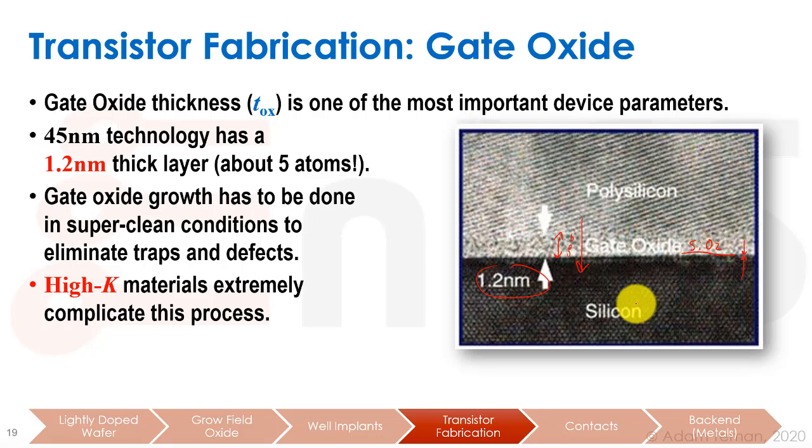There are other reasons, for example, that it's sand and we can find it all over the place, and it's cheap and easy to use. But to make MOSFETs, this interface between the silicon and the silicon dioxide was very important. And changing our materials several years ago to high K materials, which are not silicon dioxide but are based on hafnium and so forth, is taking our basic assumption of a good interface between the silicon and the silicon dioxide, throwing it away and starting over. But that's what is done now.